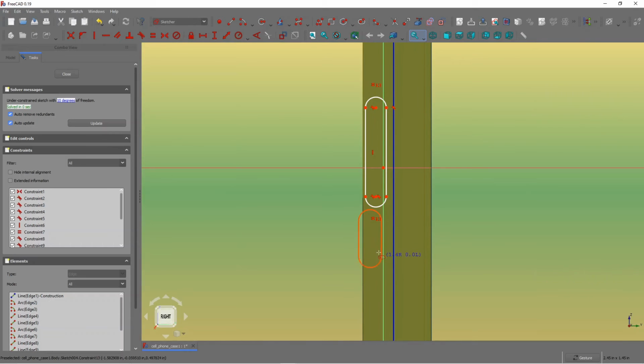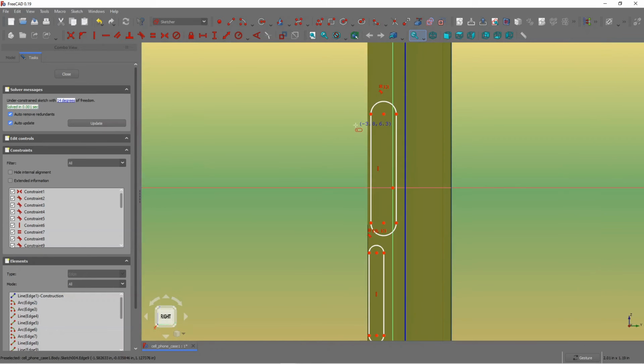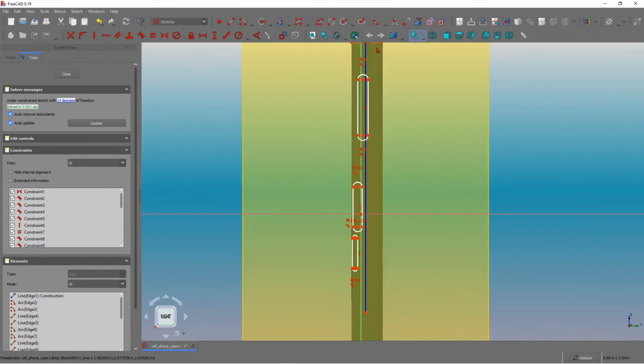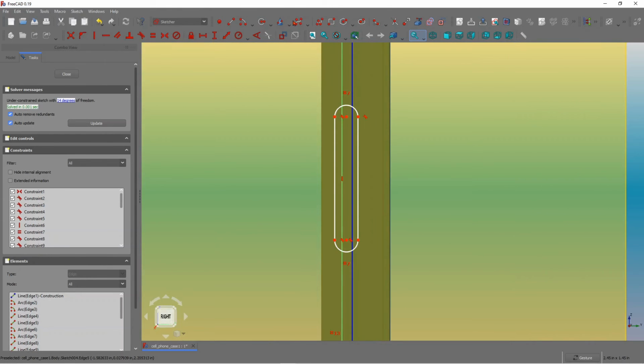Yeah, just arbitrarily draw something and then we can position them. Okay, another one here. So you arbitrarily draw them. Now what you have to do is position. So similar to what we did previously, we want to have an anchor point. The anchor point is the center or the centroid of this. Okay, I didn't do that correctly. Let's put an arbitrary point here, and then using symmetry we center it. Okay, so now it's centered.